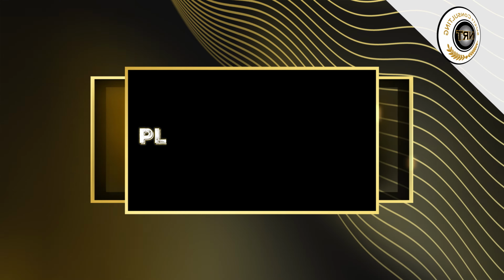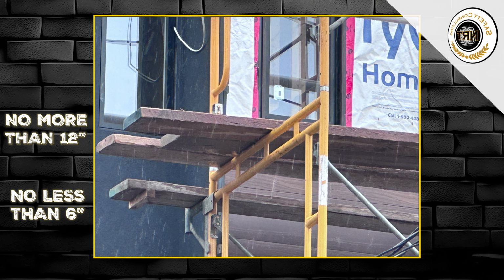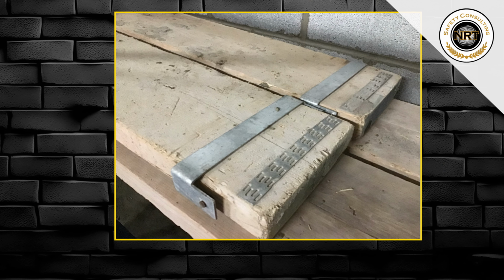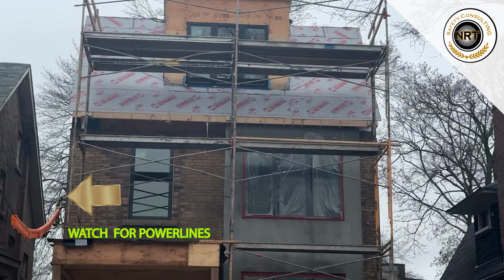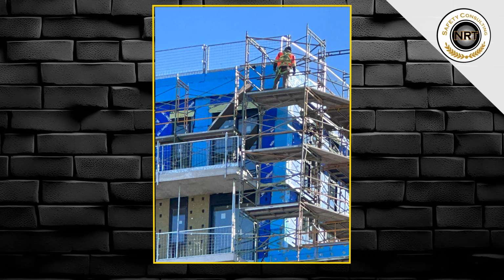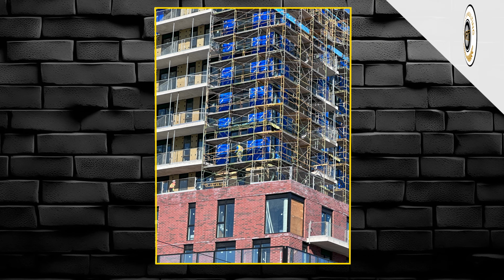Platforms should be laid tightly planked from end to end for the entire width of the scaffold. Ensure that planks are secured to prevent slipping from their supports, using tie wire, cleats, or any other type of securement. All work platforms must be free of unguarded openings to protect workers from falls.